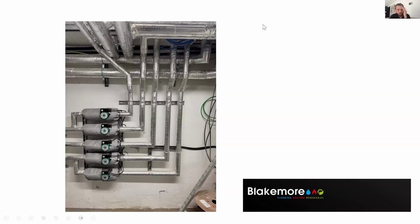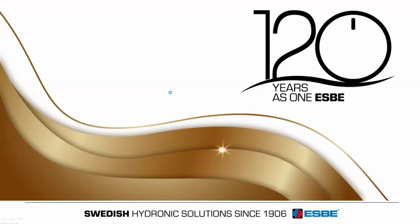It's just always looking at ways to improve on every job. I think that'd be the biggest improvement: to use weather comp on the secondary and fixed flow on the primary in times of low tariff, which you could do from his KNX system. So that's a lot of information. I'm a bit sporadic with it, but thanks a lot, Damon.